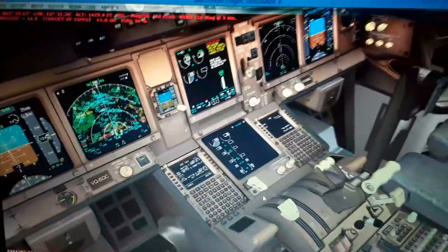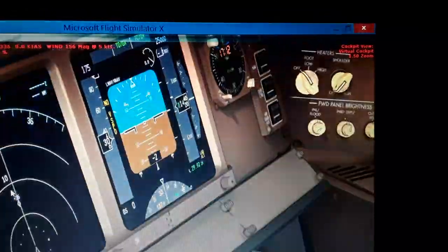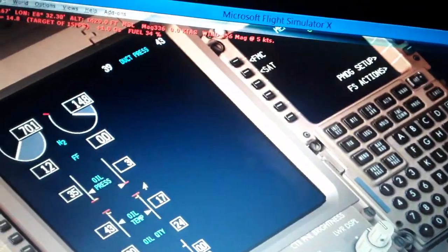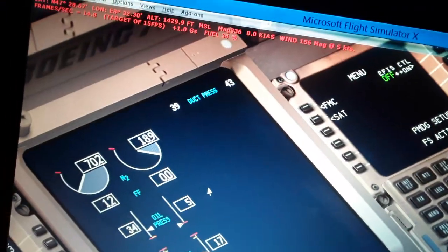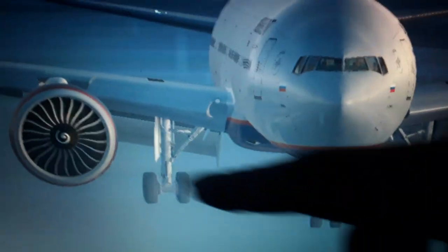So we have the other side engine now still, as you can see. So we have to start very quickly. You can hear in the overhead panel here in this switch, in the start position, we have the right wing engine start process now. The FADEC is working, so we have also the engine starter compressor from the APU, 33% N2 stage. You can see the spin is increasing for the right wing engine.